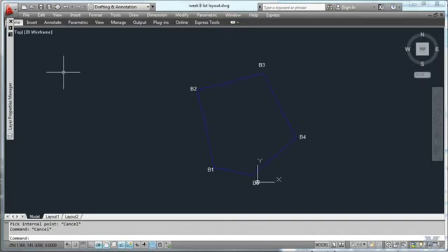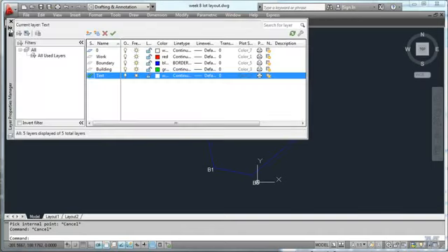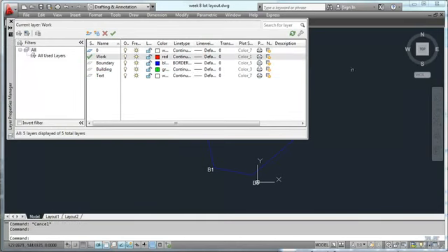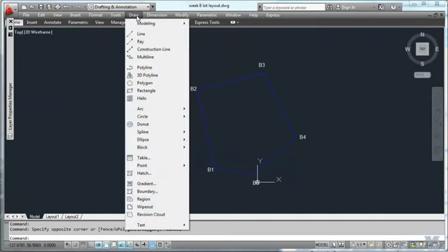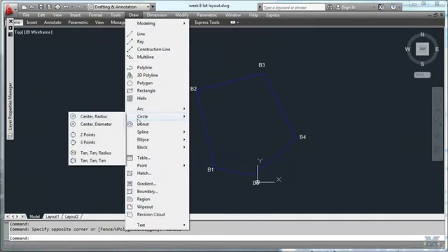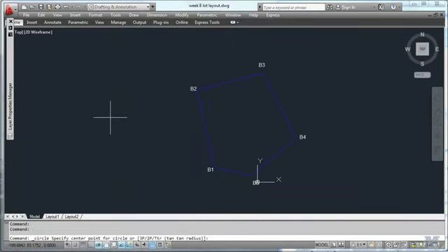Alright, CAD fans, following from the previous video, we're going to add the building to this lot layout from my surveying notes. So let's see. Get the layer thing out of the way. I just switched to the work layer because I'm going to use the circle tool, center and radius style, to draw in, we used a tape measure from corners to figure out where the corners